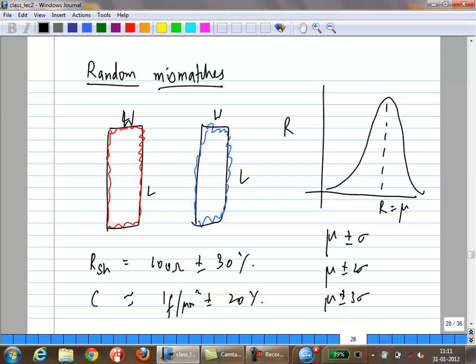If you look at it from an overall process point of view, depending on certain process parameters, over time or between different wafers, you could have changes in doping levels, or changes in other things, which can also affect the resistance value or the capacitance value or anything. So you have to make a clear distinction between systematic cases and random cases. Just wanted to point that out in case that was not clear.